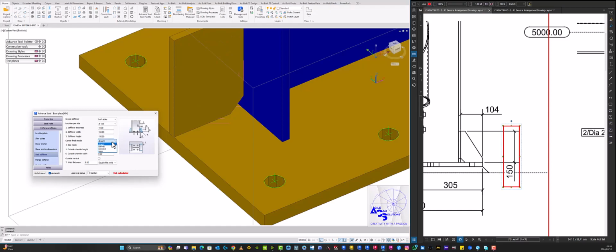And then corner finish, straight or concave. You can choose whether it's straight, and if it's concave, you can put the concave. Usually it's straight to allow the weld to run, because if you remove that corner finish, your stiffener is going to be kind of wedged, because it's going to be sitting on top of the welding that was done for the column and the base plate.